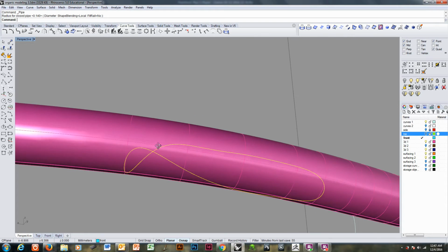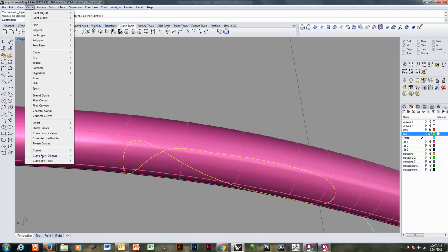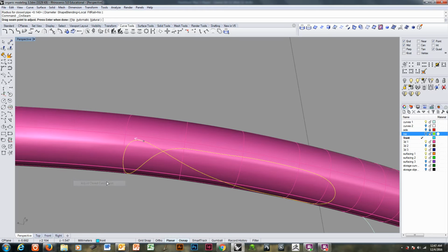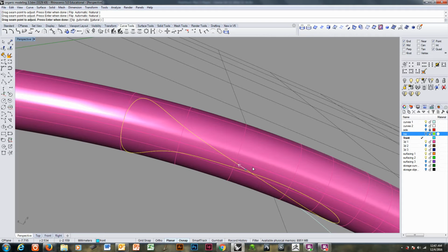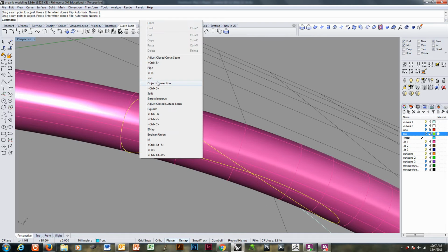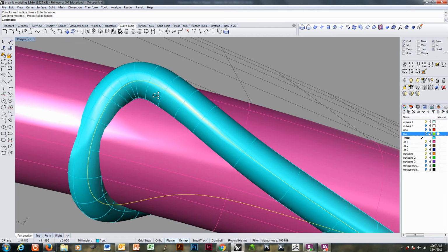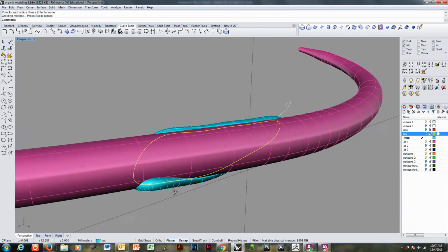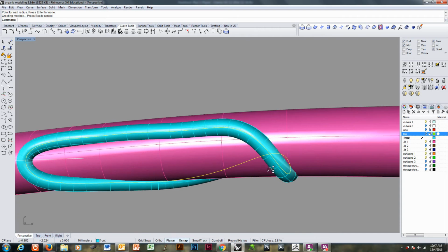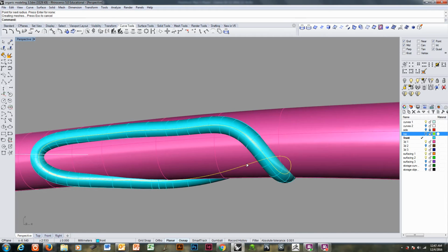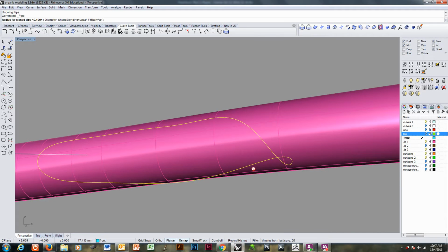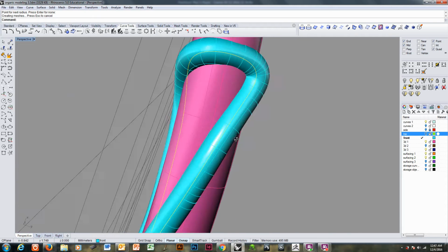I also don't like where the seam is. Gonna move that down here on the bottom in a fairly straight area. I had it at 0.14. I'm going to put it at 0.1. Okay, that's not bad. Actually, it's too small. 0.15. We'll just deal with the corner later.